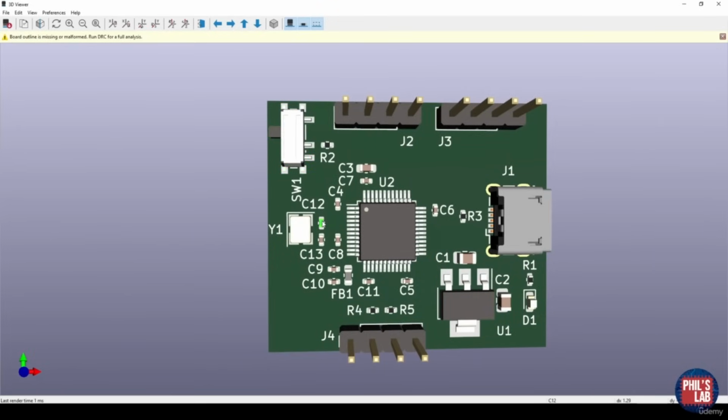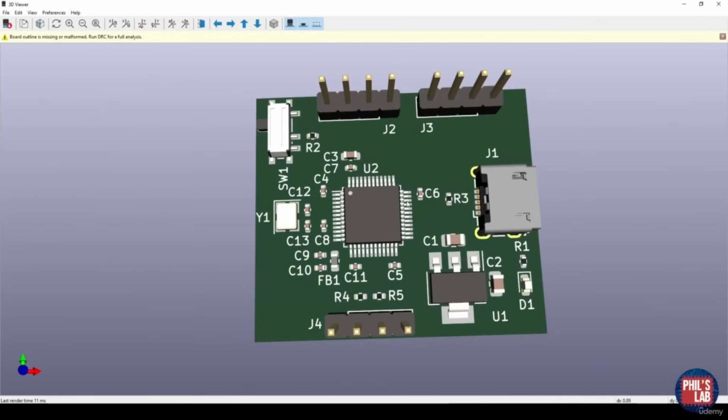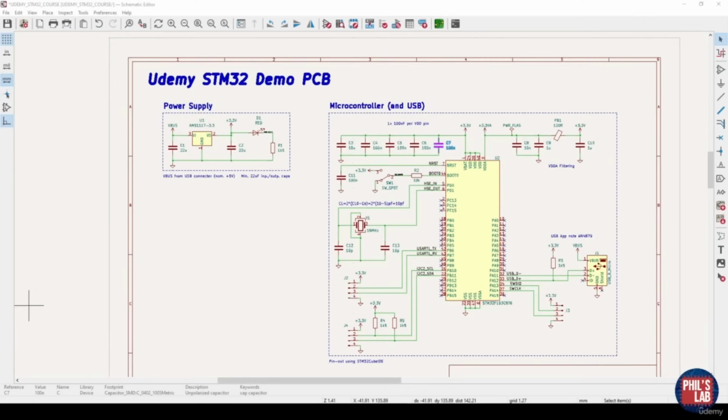We also have to add mounting holes, so let's do that in the next step. Then narrow in on our layout, adjust the connector positions, and make sure we have a really nice and neat layout before we start with routing. So we want to add some mounting holes in case we want to put this in some sort of enclosure or something.